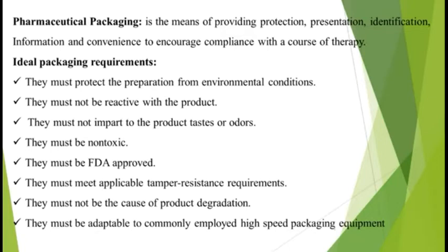And next, plastic containers are made up of, the fourth is polystyrene. So the polystyrene is not useful for liquids, and this polystyrene has high water vapor transmission as well as high oxygen permeability, and it is used for dry products only.